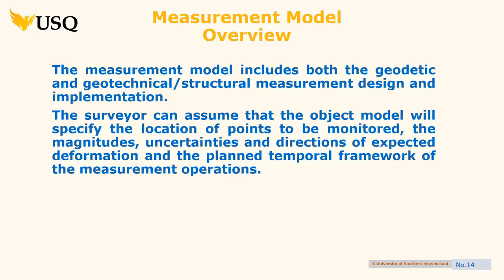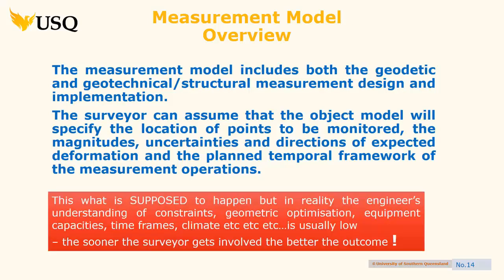You've got to be the professional and go, okay, you want this, like in that thing of plus or minus 10 millimeters to the other buildings. You should query that and go, well, all the other buildings, or just the ones nearby? Most runways are 3,000 meters, 3 kilometers away. Do you actually want 10 millimeters between those? Or is it only around the hangars? You can ask those questions.